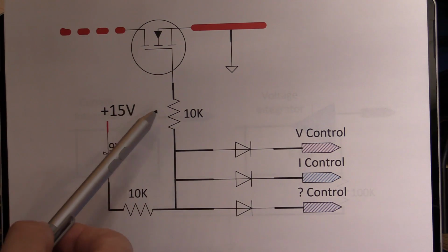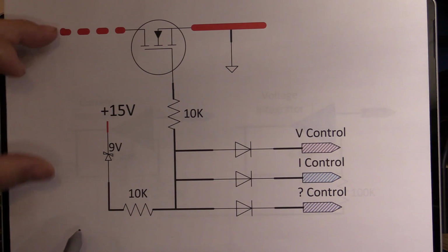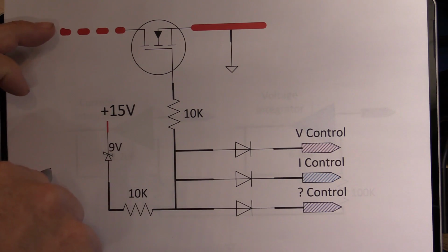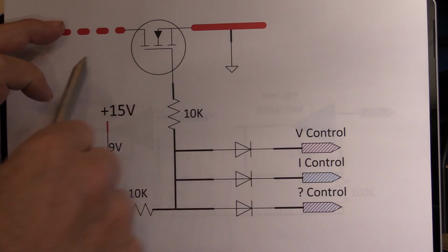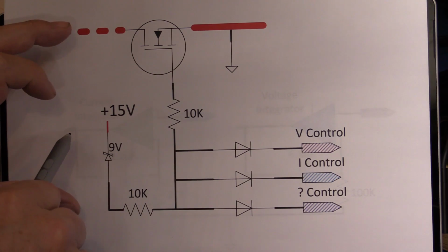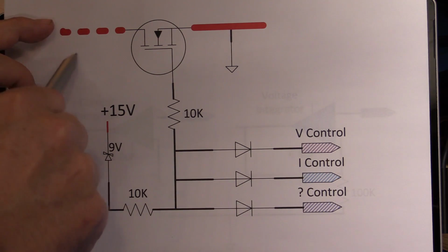Remember, in our earlier videos, we had our op amps basically sitting across the supply. So between ground and this point, that was say 35 volts. You had to have op amps that were capable of working with 35 volts or 40 volts or more, depending on what your output wanted to be. But the problem with those circuits, and some of you have tried this and seen the same thing, is that you can only drive up to about 1 volt less than the rail.